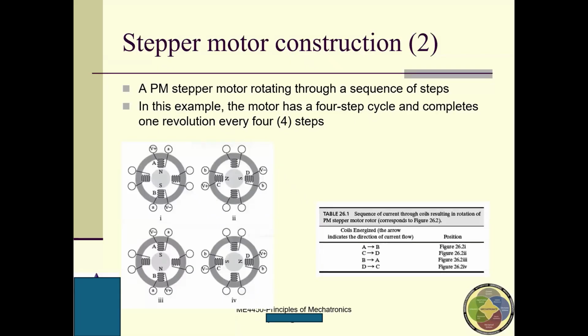Still using the right-hand rule, this is N, here is S, here is N, here is S. You can just think N, S, N, S. Then this field disappears, and this N will be attracted to this position, and this S will be attracted to this position. As a result, in the second instant, this is the orientation of my output shaft. Make sense?